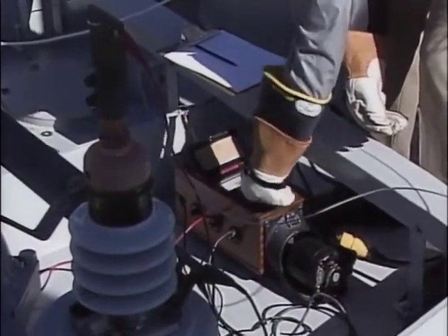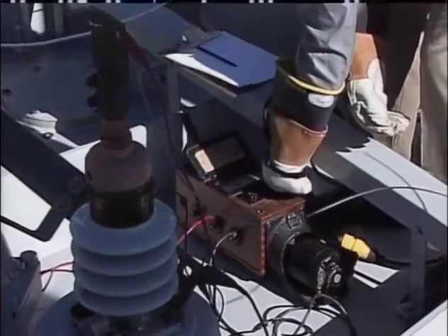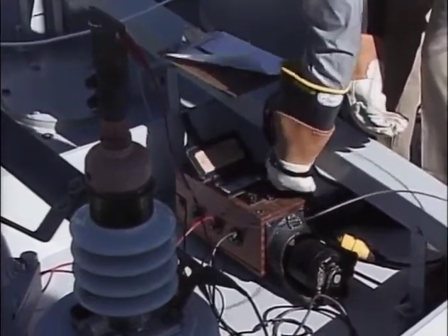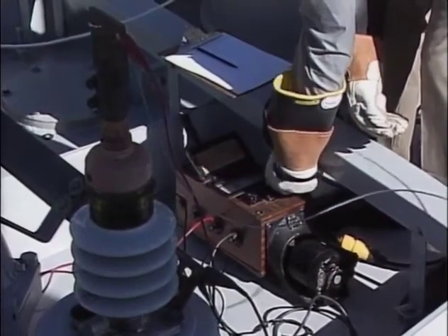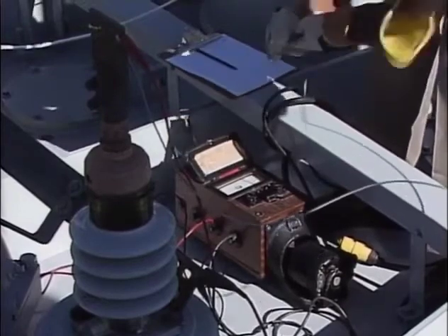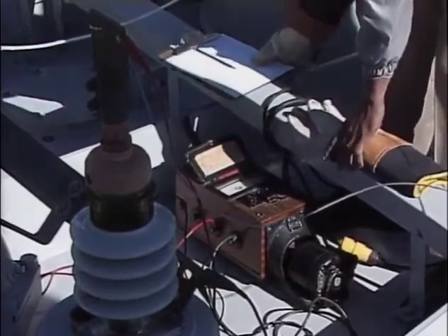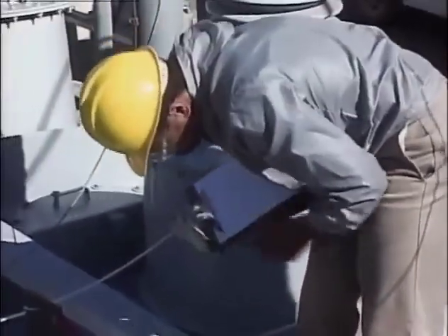The voltage setting of the megohmmeter is adjusted to a value below the rated voltage of the reactor. The megohmmeter is energized to apply a DC voltage to the reactor. A caution is needed here. The megohmmeter provides enough DC voltage to the reactor to cause a serious shock. For your safety, stay away from the reactor terminals while the test is being performed.